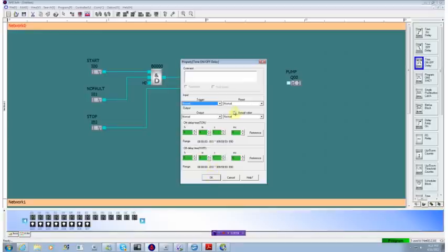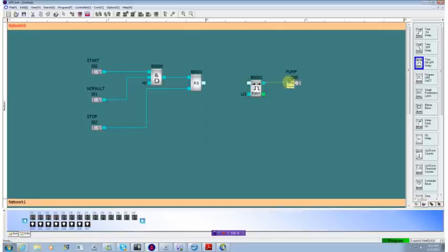and we see that we have a reset capability. We don't really need that right now, so we'll just leave that at permanent low level. We have an on time and an off time. We'll set our on time to say 3 seconds. We'll set our off time to 2 seconds. We'll connect our output through to the pump. We'll connect our input to the trigger.